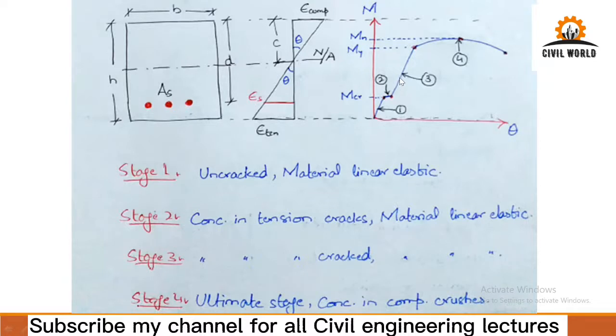Concrete in the top fiber is taking compression, and all these tensile stresses are taken by steel till a point where steel starts to yield. So this is the yielding moment, My, and at this point there is a greater increase in the strain and a lower increase in the moment, and it then follows the profile and reaches this maximum point, which is termed as Mn, the nominal moment capacity of that particular beam.